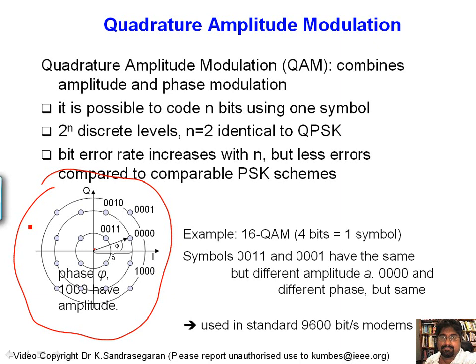And if the transmission medium gets even worse, you might drop down to QPSK and down to BPSK. So the modulation scheme that is being used can change as a function of time based on the channel conditions. Because remember, the more noise there is in the system, the more likely the two phases are going to interfere with each other.